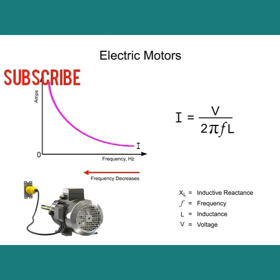As the frequency decreases, current will increase. Motors are frequency sensitive, which means that frequency changes can cause speed changes within the motor. If frequency decreases significantly, the motor may experience a large increase in current, which can cause motor components to overheat.